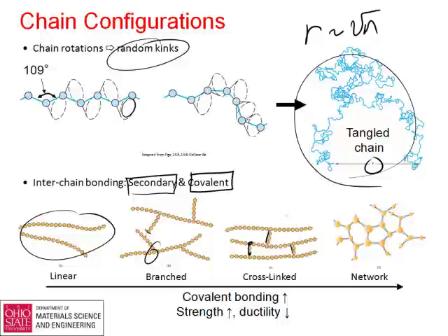So you can imagine what happens if you take a structure like this that's cross-linked and you heat it up: there's very little attraction between these chains, but they're stuck together. Just as a bit of foreshadowing, a cross-linked polymer above its glass transition temperature is what we call an elastomer.